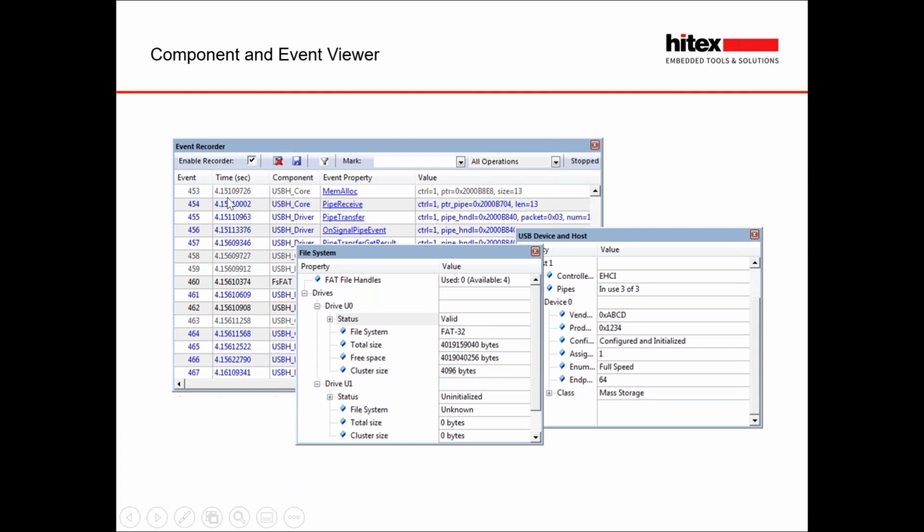We also have an event viewer. This is kind of like printf style debugging, so that we can annotate our code and then it will send up runtime information as the code executes to the debugger. So we build up a list, sort of an application trace of how our code is executing. And again, time spent on both of these provides you a lot of extra detail and information when you go to debugging.